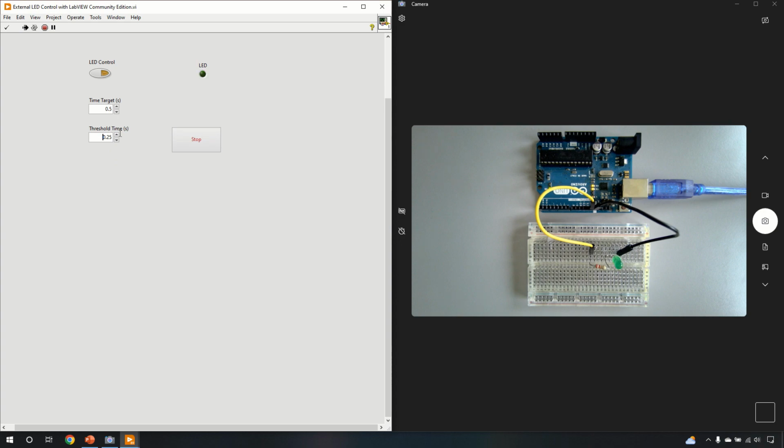If you want unequal amounts, I can simply set the threshold value, let's say here, to 100 milliseconds. Then my LED will turn off for 0.4 seconds and on for 0.1 seconds, or I can do the opposite, just put here 0.4 to flip the timings. And this is how you can flash your LED. So for example, here I can have 1 second and I can have 0.9 seconds of an on time or 0.1 for the on time to have a blinking LED.